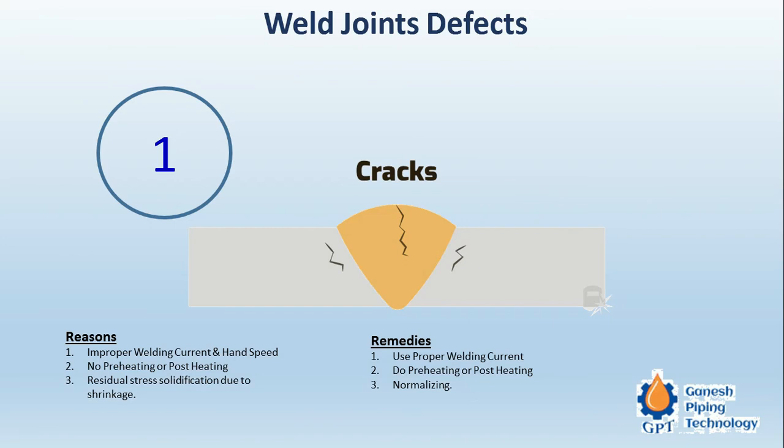So the metal deposited by the filler electrode will immediately get solidified, and because of that there will be a crack. For the remedy, use proper welding current.